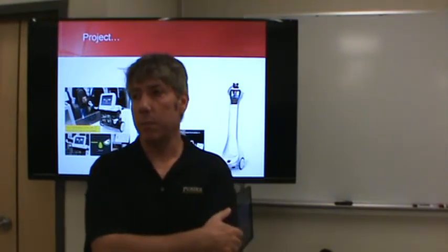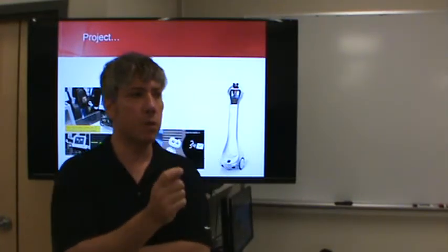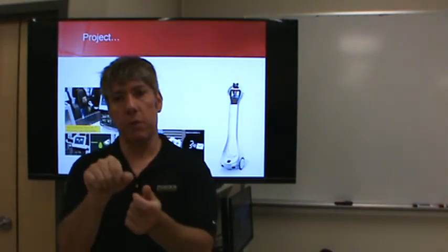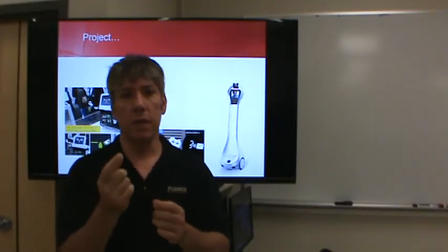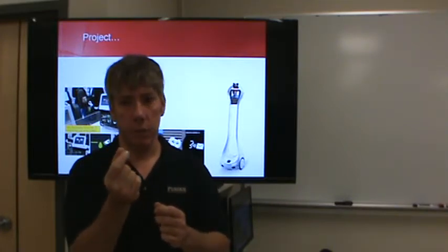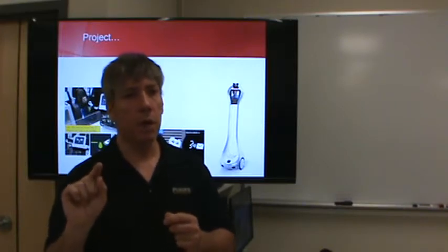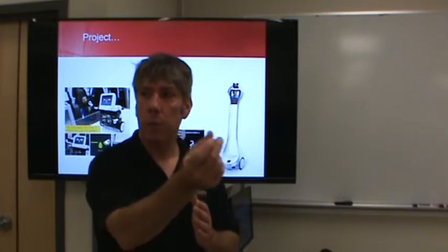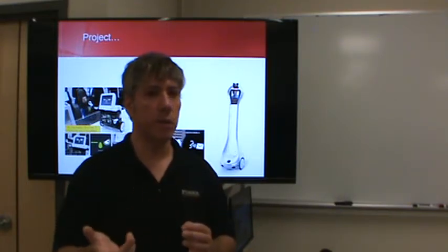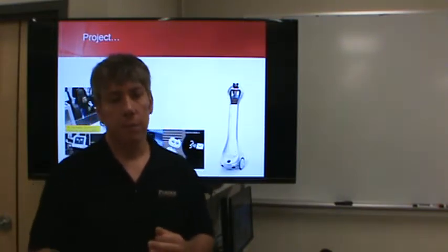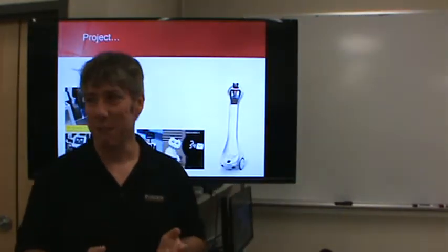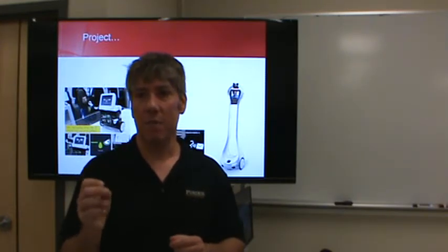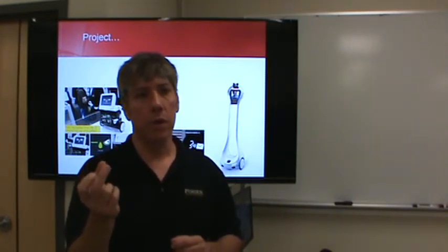So we made the pinball machine play itself. And the way we made it mechatronic, the precision mechanical aspect, we built a device that would retract the plunger, and the goal was to make the plunger retract to very precise amounts, which we succeeded in doing, so that when we shot the ball into the playfield, ideally we would find a path, an amount of speed or whatever, that would hit a lot of targets on the way down. That was part of our strategy for maximizing our score. It turned out it really didn't matter where you shot the ball into the playfield, you got about the same result. But we did end up having a mechatronic system because we could control the position of the